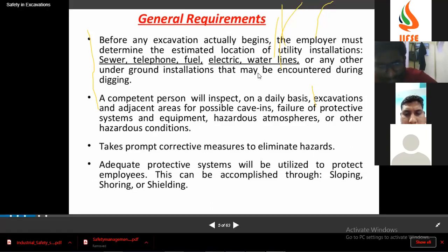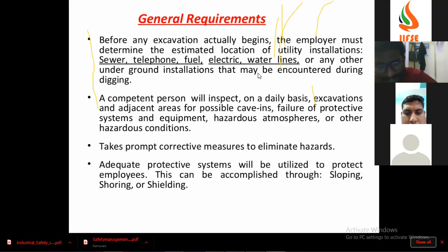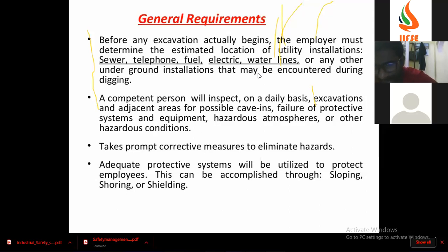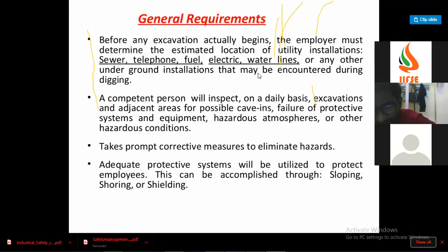Yes, benching supports to check, sir. Yes, we have to check on a daily basis, because if some excavation happens tonight, tomorrow morning the situation will change. So on every shift, what are the possible points he should see? The cave-ins. Collapse, sir. Is there any possibility the excavation may collapse? Yes. Is there any possibility of cave-in?